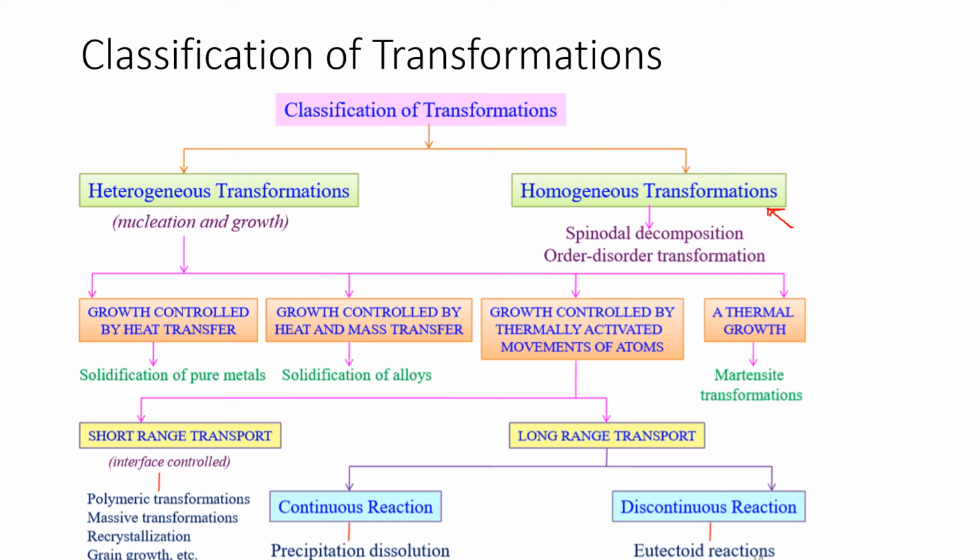Homogeneous needs supercooling, while heterogeneous forms at structural inhomogeneities, like container surfaces, impurities, grain boundaries, and dislocations in the liquid phase, which is much easier since a stable nucleation surface is already present. It requires only slight supercooling, between 0.1 and 10 degrees centigrade.